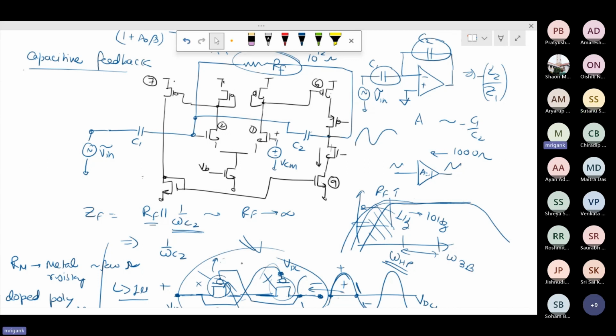If you use an ideal resistor, it should work. If you use this resistor, it will have a problem. So you can at least simulate using the ideal resistor. Otherwise, you have to design the whole op-amp in this technology. So first you use the ideal resistor and see what value is coming. And you can try to simulate with this one, try to increase the channel length for the cross-coupled transistor, and see what value you are able to get. And then based on that, you can estimate.